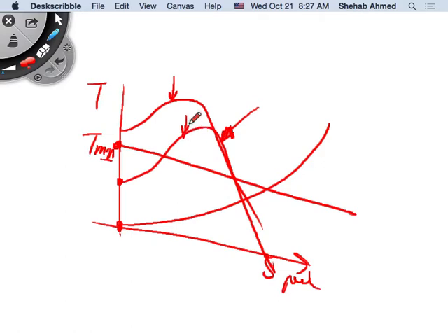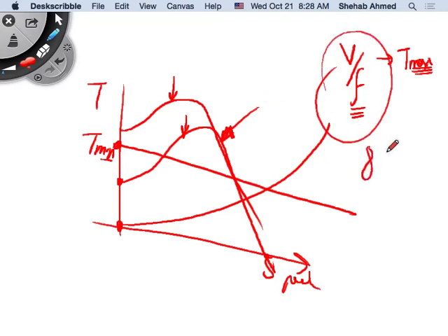If I'm using this application of gradual application of voltage, then I'm not maintaining the V over F ratio constant, meaning I cannot operate the motor at max torque anytime. If you're able to operate motors with V over F constant, then you can control torque easily in the motor. And this can be done with what we will study in chapter 8, which is power PWM inverters. We will study how we can change voltage and frequency. But in the AC voltage controllers chapter, we will study only how we can change the voltage that we apply.